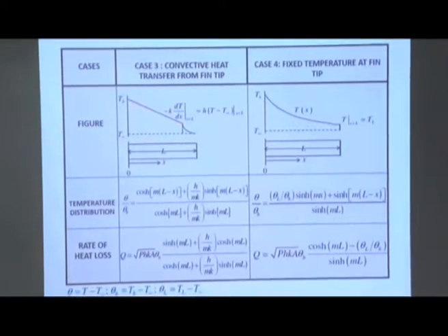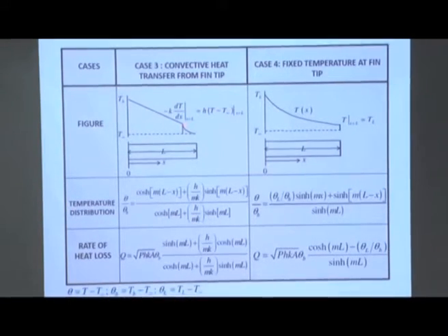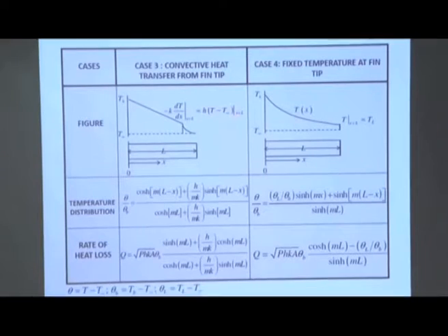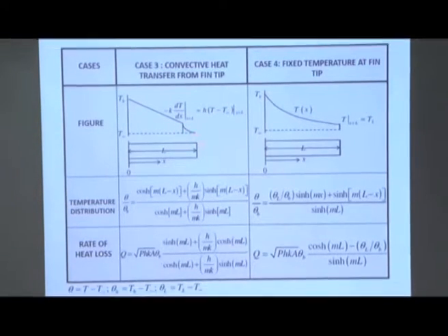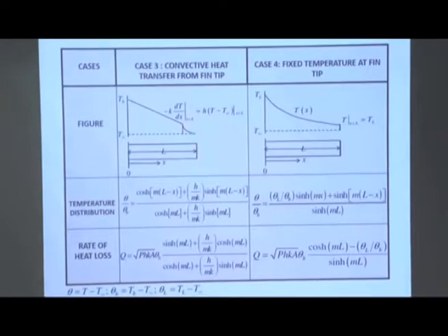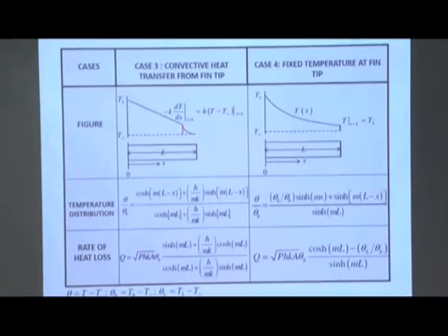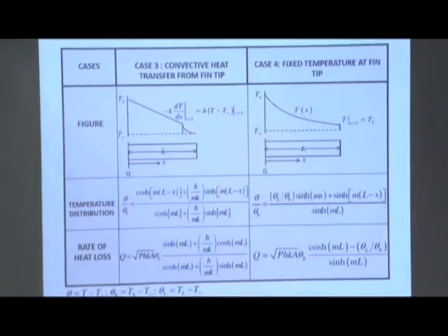So therefore, here what happens, the temperature changes and it has a slope, not zero slope, which determines the heat transfer, minus k dT/dx, and should be matched with the convective heat transfer at this interface, that is this solid exposed surface with the surrounding gas, so that this slope is matching with this. And this is the temperature distribution by convection after this. That means from this surface there is a decrease in temperature in a thin film due to convection, which will be dealt with in detail in convection classes, the first class when we take convection heat transfer. So this comes to T infinity.